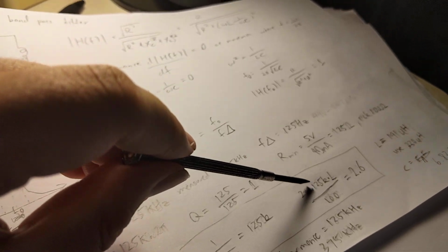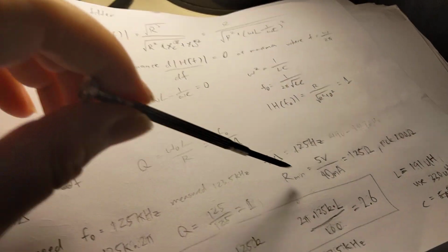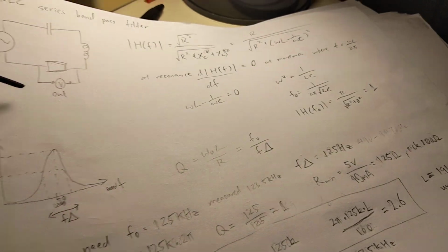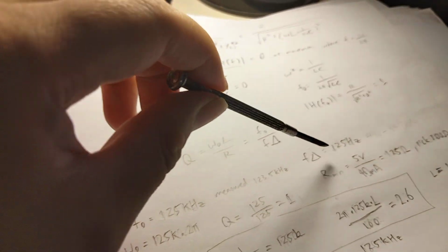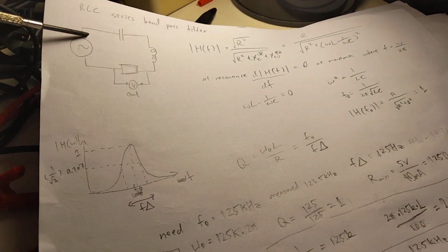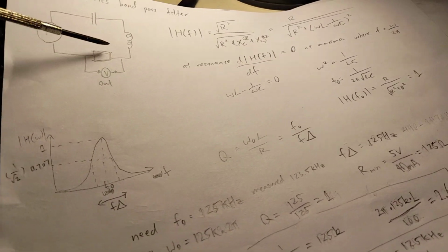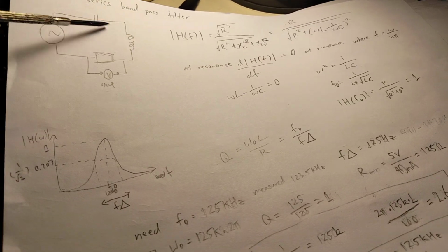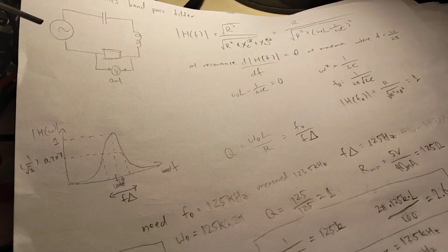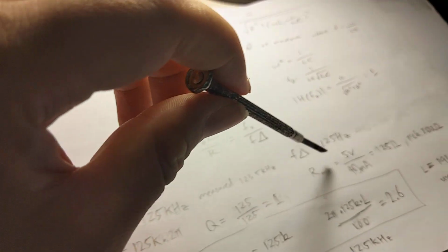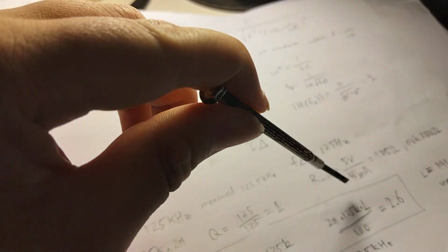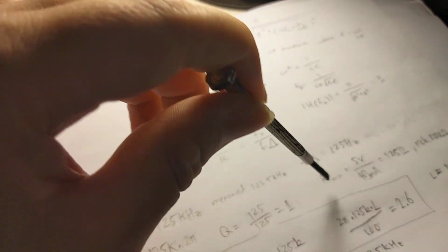And so essentially what I ended up doing was, there is a requirement for the resistance, because if the resistance is too low, the resonant frequency current, which won't be attenuated by the LC filter, will result in a current that's too large and will burn my Arduino.